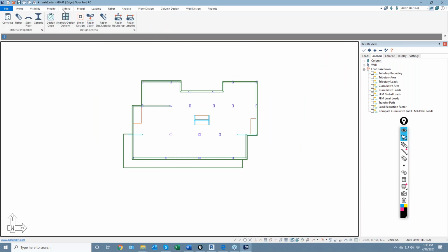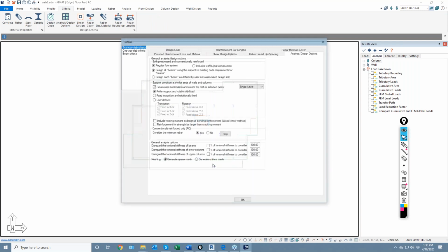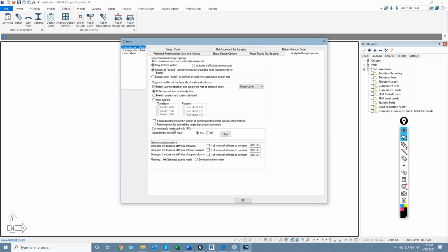And coming back over to this, just to kind of close that gap, if you add enough rebar in a bottom or top mat to meet the requirements for temperature shrinkage, then I would just turn this off. There's no need to have this on. If you've already added it, technically the program wouldn't add it for that particular purpose. It might add additional rebar if the calculated amount of rebar doesn't meet spacing requirements.